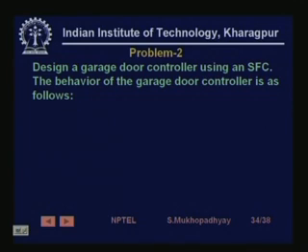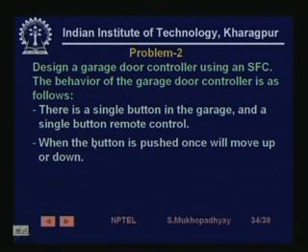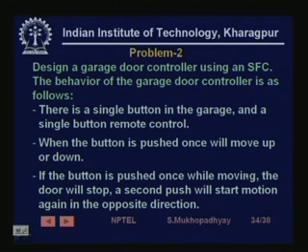So the next problem says design a garage door controller using an SFC. The behavior of the garage door controller is like this. There is a single button in the garage and a single button remote control. When the button is pushed once, the door will move up or down. So you push it once, it will move up or down. If the button is pushed once while moving, then the door will stop, and a second push will start motion again in the opposite direction.